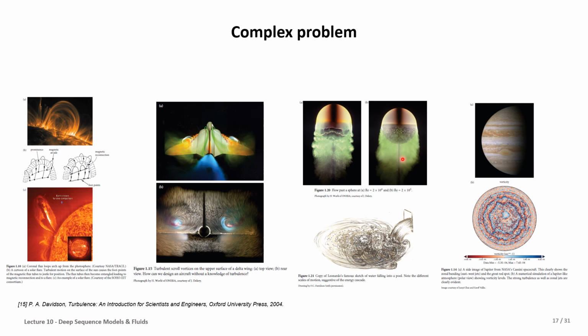Sometimes turbulent flow could be used as a tool. For example, when we want to do mixing with two fluids, turbulence can make the mixing rate faster, and as well about the separation behind the object. Sometimes we make it turbulent because it's better performance when dealing with the separation.